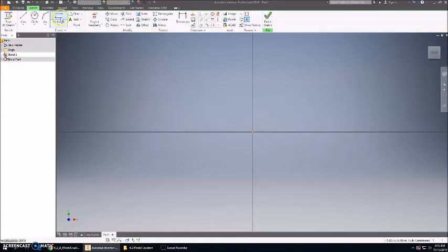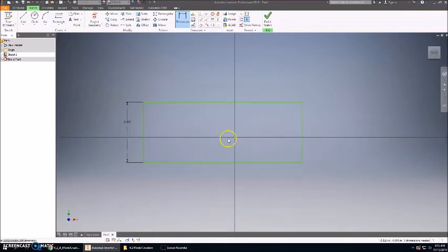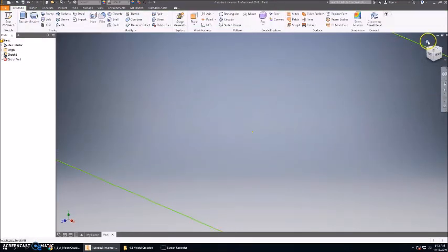So we're going to come back over to Inventor and grab our rectangle tool and click. Then we are going to dimension 2. Again, it's going to expand, so we're going to zoom out by 7. Once we hit that 2 by 7, we're going to finish our sketch, hit our home key to be able to recenter in our screen. We're going to extrude.